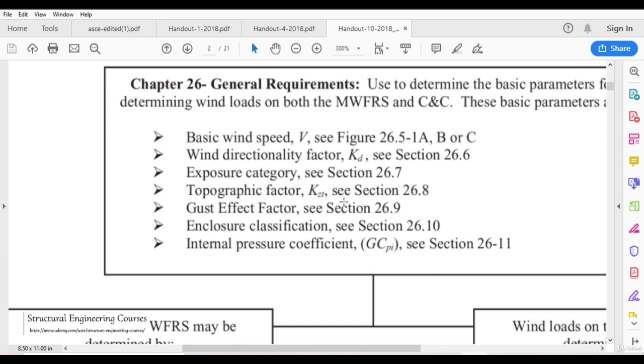The American standard guides us that for rigid structures, that is, concrete structures of low height, we can consider G equal to 0.85. Notice that this G is less than 1. Why? Because for rigid structures, the damping, or the wind absorption in layman's terms, is quite high for the wind. The absorption rate is high, so the G value is less.